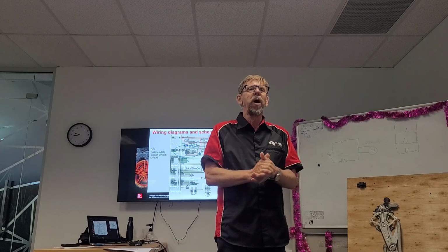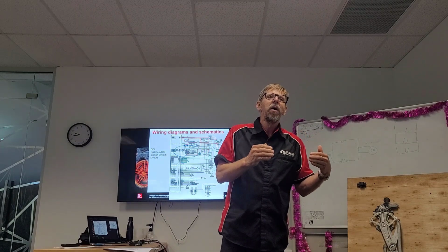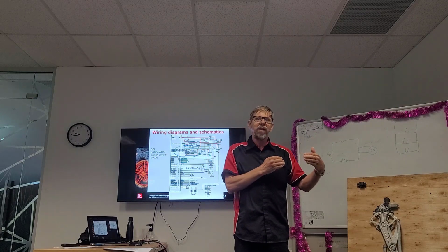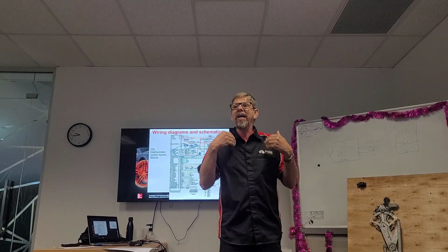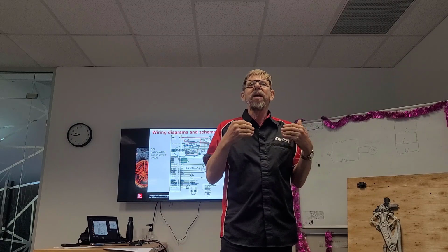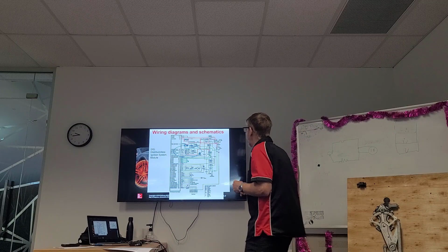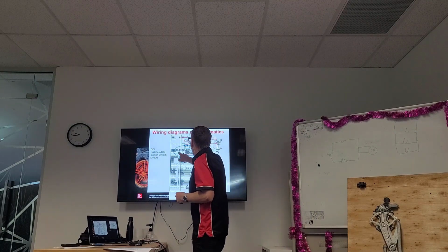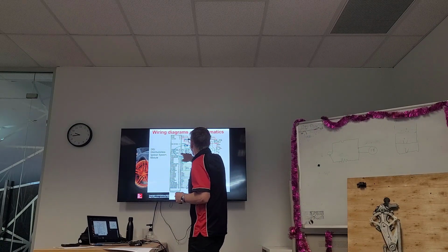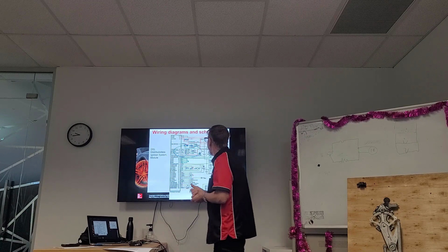Okay. So we will start the car with a static timing setting that's set in the factory. Once the car gets over a certain RPM, then the EST takes over. So that's what that is, okay? Just so you know. We know there's an ignition bypass control circuit.